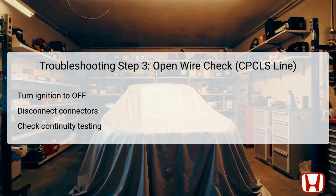Step 3 focuses on performing an open wire check on the CPCLS line to investigate any connectivity issues that may be contributing to DTC P0970. Begin by turning the ignition switch to the off position. Using the HDS, jump the SCS line for diagnostic purposes. Next, disconnect the solenoid wire harness 8P connector from the engine wire harness side and the PCM connector B51P.